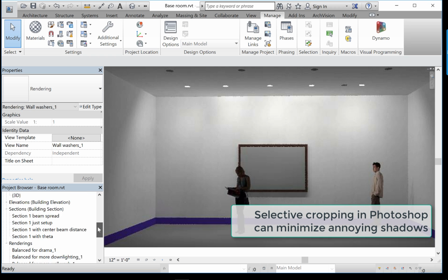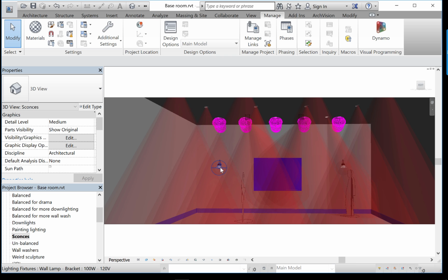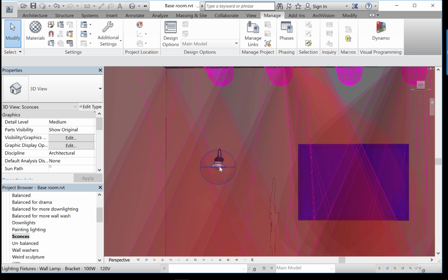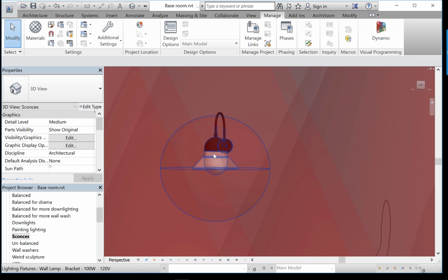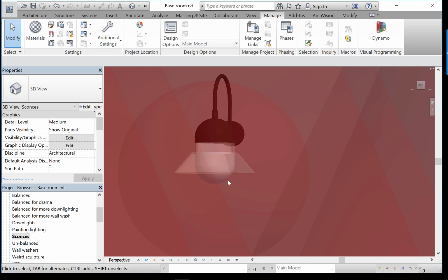And then take, say, the view from Revit where these fixtures are on. You could even turn off this light fixture, so that it's not emitting light, and just make, say, this cone, this jelly jar shape glow, or if there's geometry inside this fixture, which I'm not entirely sure there is, but if there was, you could make something glow inside this, as if there was a lamp inside of a glowing glass jar. And then Photoshop the two together.